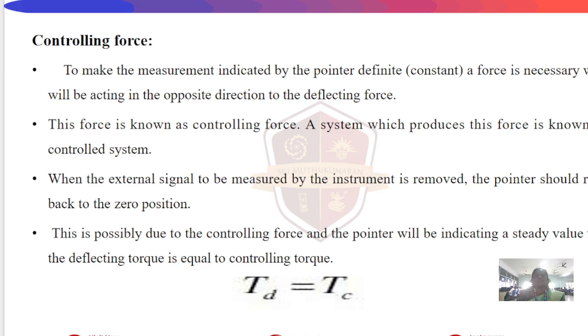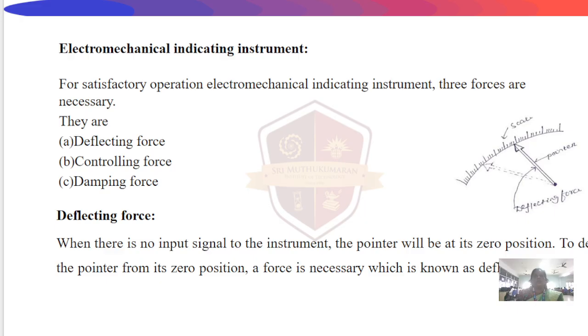Deflecting force. When there is no input signal, the pointer stays at zero. When an electrical quantity like current flows, deflecting force is produced. This force moves the pointer away from zero. So basically, the deflecting force is responsible for moving the pointer according to the input signal.